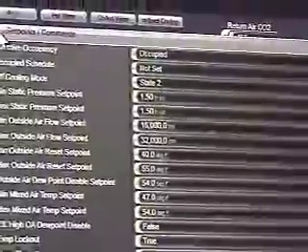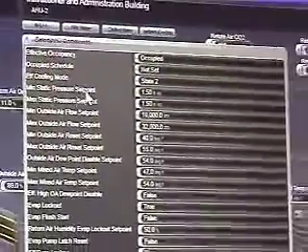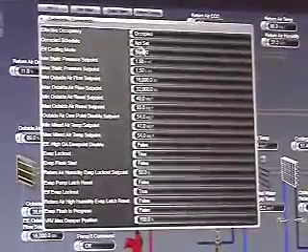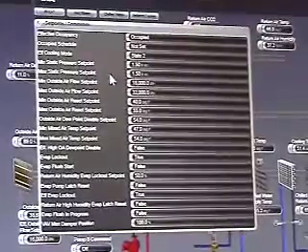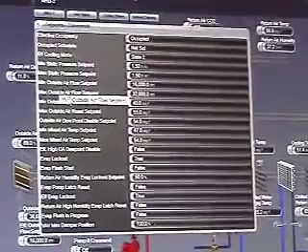Here we have the set point block. It gives you the ability to look at quite a few things. Effective occupancy schedule. Here's your minimum. They've set them both at 1.5 right now. Here's your outside airflow set points, min and max.